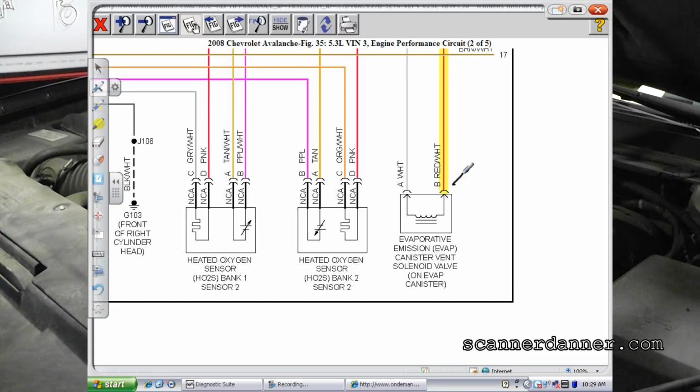The second one, this is 12 volt feed right here. And this is a switched ground, this white wire. Computer is not turning it on right now, so what should we see on the white wire? 0. No, 12. Should be 12. Does that make sense? When I turn it on, it goes 0. Well, that's right. When we turn it on, it's going to go to 0.